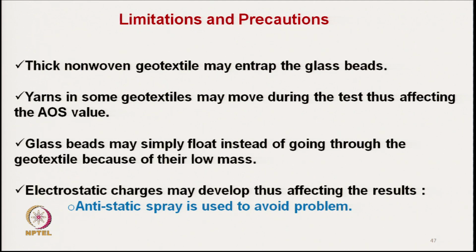Another problem is that if we use synthetic fiber, it may create static electricity and that will affect the test result, because the glass beads will get attracted by the fiber. So, in that case we use anti-static spray to avoid this problem.